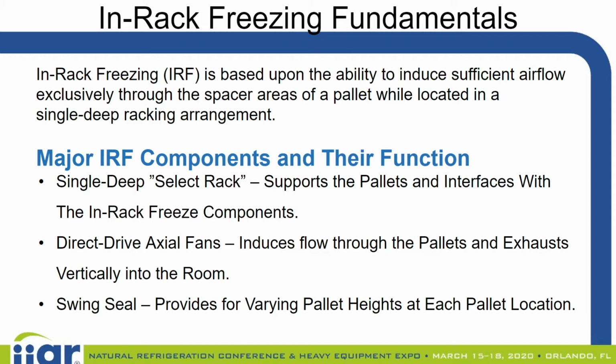And then you have the other challenge where some pallets are in a really good pathway for the airflow while others are not. So you get a vast difference in freeze performance pallet to pallet based on where the pallet is.